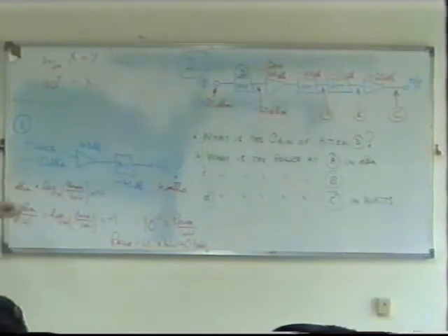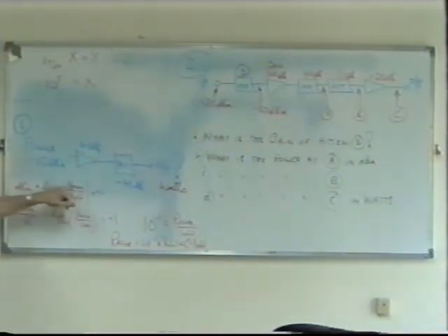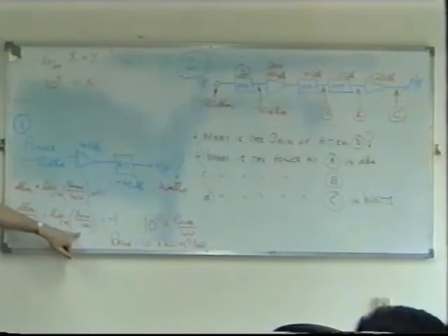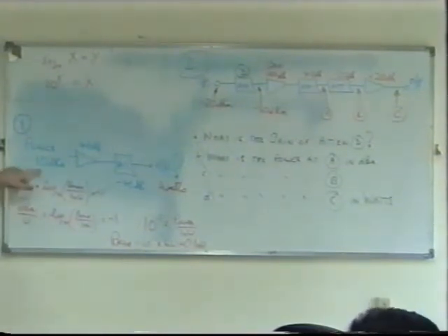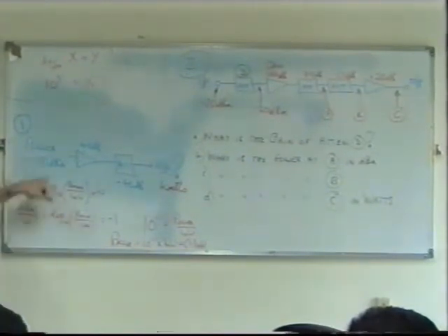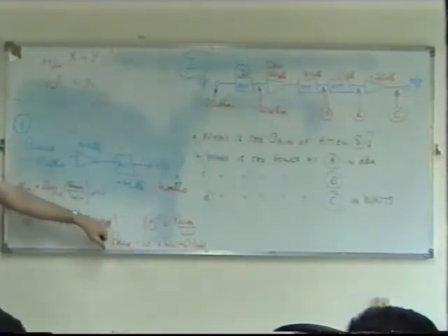Well, remember the formula that dBm is equal to 10 times the log of the power over 1 milliwatt. Now, dBm is minus 10. That's what we're told. Just rearranging this formula, dividing both sides by 10, therefore dBm over 10 must equal the log of the ratio. And of course, minus 10 over 10 is minus 1.